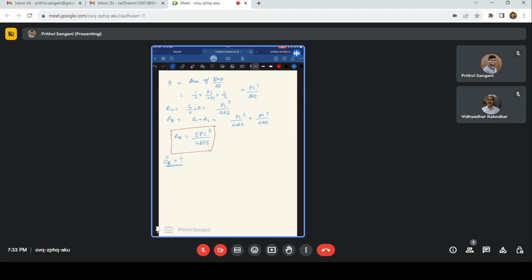Okay, so just a hint. Let me say what equations we need and what the redundants are, let me check the static indeterminacy. This is a fixed-roller kind of support. So what reactions do we have here? We have the bending moment MA, the shear force VA, the horizontal force HA, and here we have HC and MC.